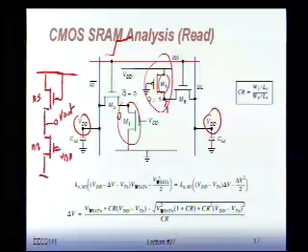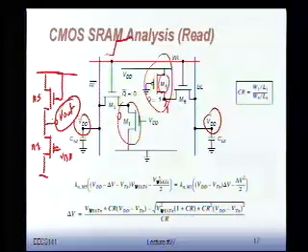So suppose now that I want to make sure that this node V out, what's the necessary condition for the cell to flip? Any idea? What has to happen for V out before the cell might start flipping around? Which we don't want to happen, right? We want to keep it in the same state. V out is supposed to stay at 0. What will make the positive feedback kick in and maybe move the cell into another state? What has to happen with V out? It has to go up. How much? 50% if it really is a symmetrical situation. So V out has to become larger.